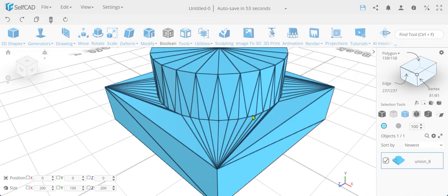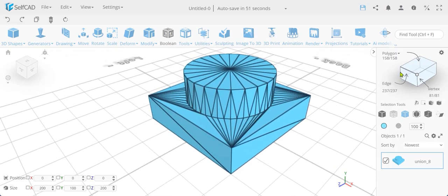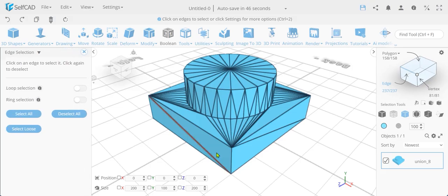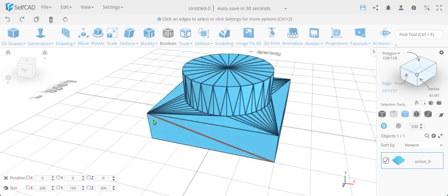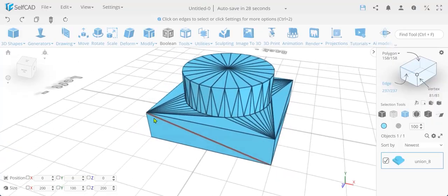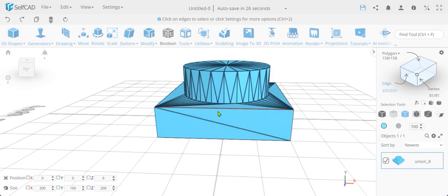This is perfectly normal after Boolean operations, but it also introduces our first challenge. Try using loop selection again. You'll receive the message, "Please select only quads for loop selection." Since the topology is no longer entirely quad-based, loop selection can no longer identify a continuous edge loop. This limitation isn't specific to the bevel tools. It's simply a characteristic of loop selection, which requires quad topology to function correctly.